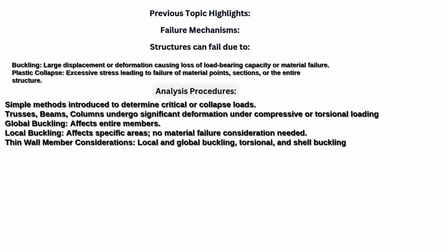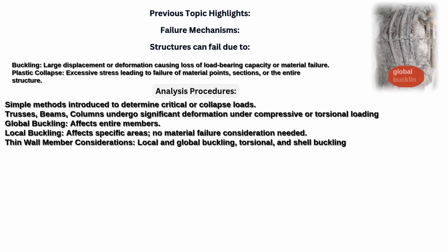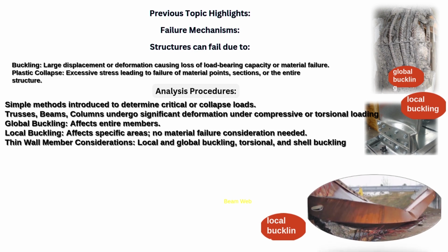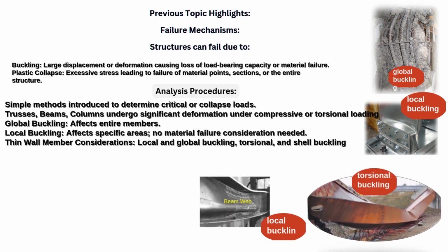Structures can fail due to buckling, large displacement or deformation causing loss of load-bearing capacity, or material failure. Plastic collapse: excessive stress leading to failure of material points, sections, or the entire structure. Analysis procedures: simple methods are introduced to determine critical or collapse loads.